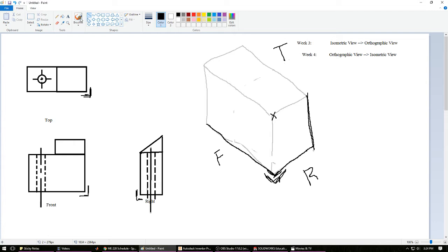Center line. So in order to draw this, we know that there's a hole somewhere. This seems as if there's an inclined plane somewhere. So we have these three baselines, and we need to fill in the rest of it. Let's say that it goes up to a height of here. This is the corner right here. That's the height it will go to. Usually you'll have this either gridded out or you'll know the dimensions. And so we know that looking between the front view and the right view, this actually extends all the way out like this and goes back down.